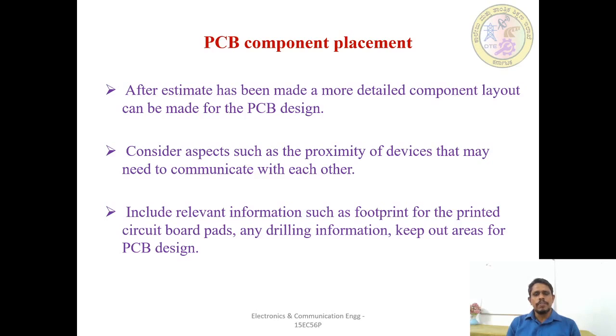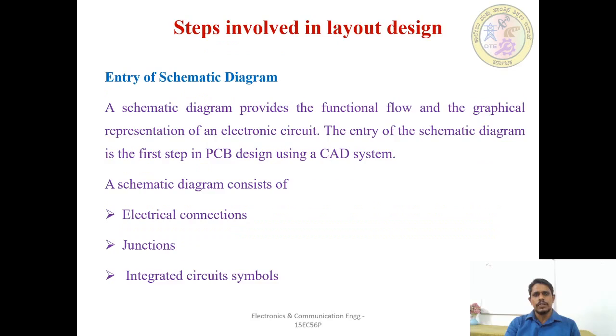Include relevant information such as footprints for the printed circuit boards, pads, any drilling information, keep out areas for PCB design. Drilling information, keep out areas and board pads, all those things have to be discussed with each other, and the final decision has to be taken.